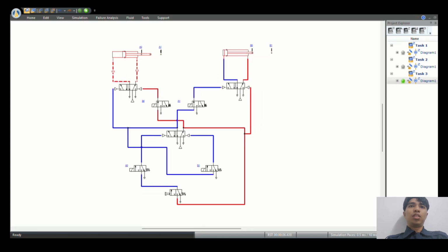To implement this, I designed the pneumatic circuit in Automation Studio. It includes two double-acting cylinders connected to directional control valves. These valves are synchronized to ensure the proper sequence of operations. A advances, then B advances, followed by the retraction of B, and finally A retracts.